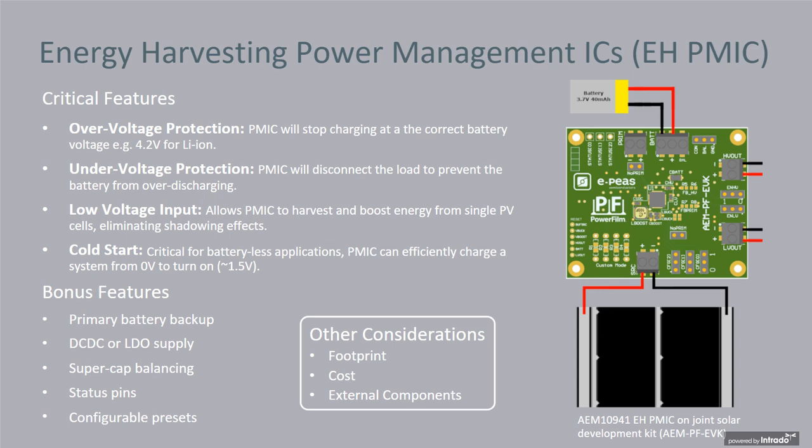Some bonus features that are really convenient for specific applications: primary battery backup, those DC or LDO outputs, supercap balancing. If you have a supercap that has multiple cells in it, you want to make sure they are all balanced. Status pins, again, communicating back to your central MCU saying, hey, here's the status of the controller, everything's working good. And then configurable presets, maybe a couple pins on the package where you ground them, and then voila, your system is set up to charge a lithium battery. That can really save on external components.